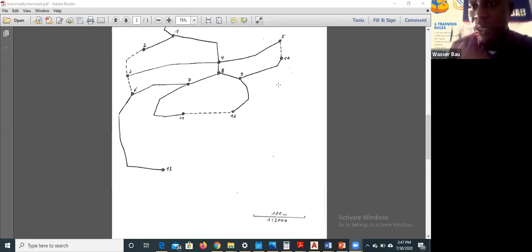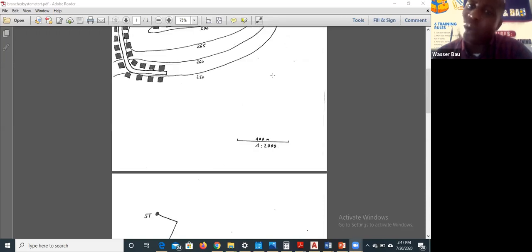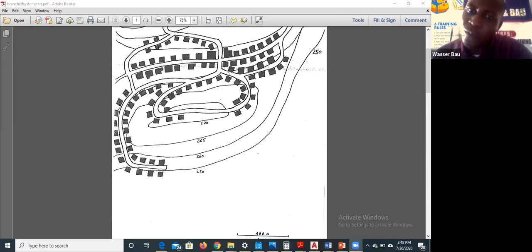Let's do a branch system. So for node 10 now, how many houses are connected to node 10? 1, 2, 3, 4. In real life, this doesn't look like a 3-bedroom bungalow. This might be a hotel or a school. So the value will not be 0.023. I have to go back and ask how many rooms are in that hotel or hospital, and what the standard says about a hospital. A hospital is about 200 liters per person per day, but the residential area is 100 liters. So you see, I have to upscale.